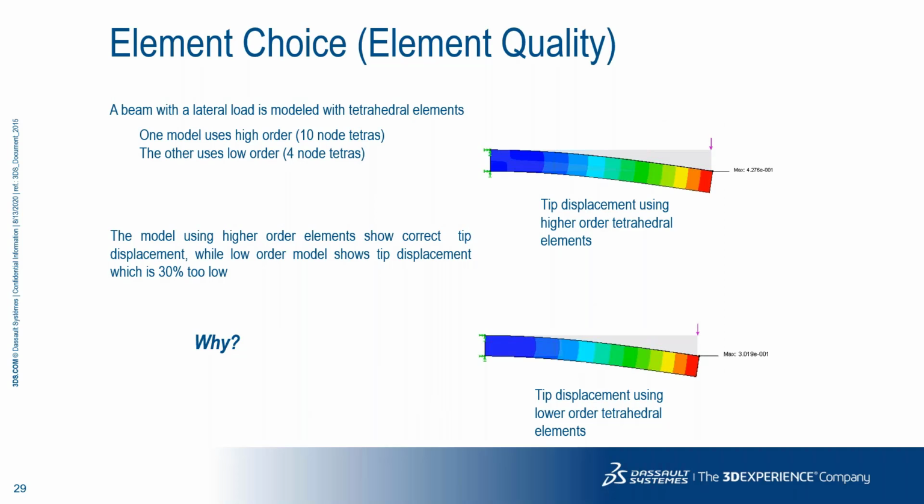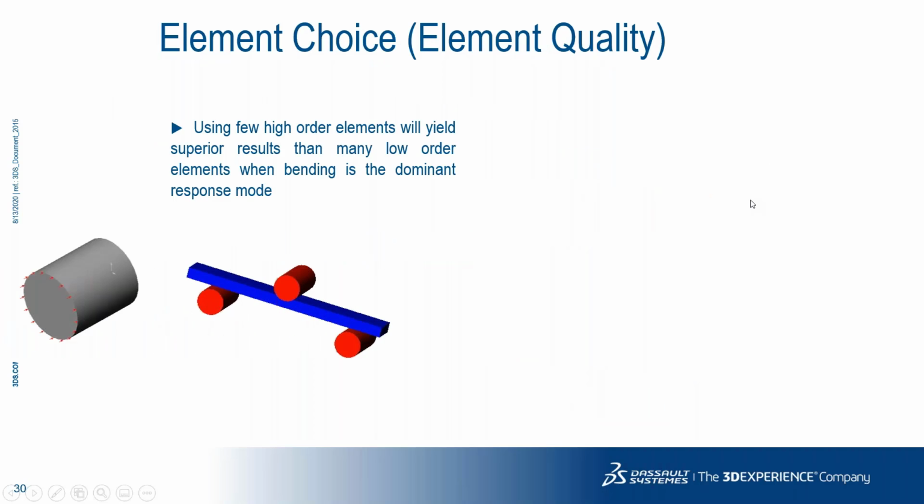So, whether to go for higher order elements or lower order elements? One example: if you take the same cantilever beam and apply a load vertically downwards on one of the ends, you will find that there are differences in your results also. So as an analyst, you should be capable of understanding how results will vary, and which elements you have to use.